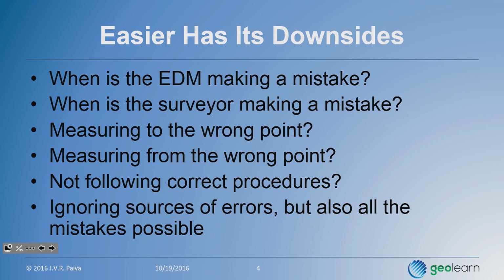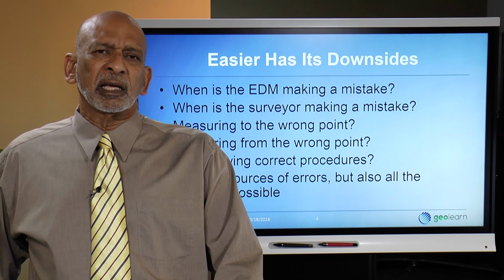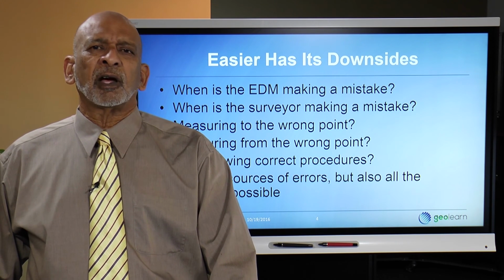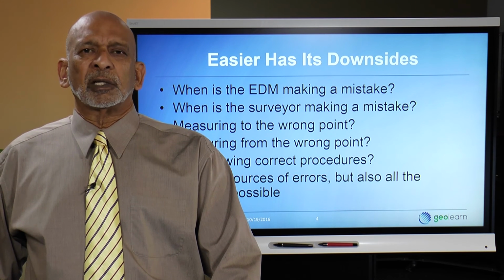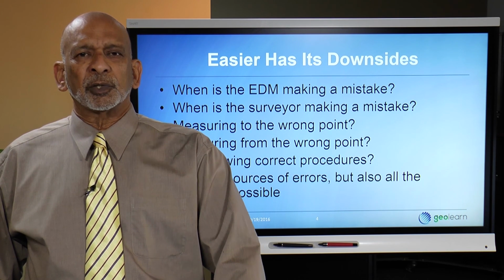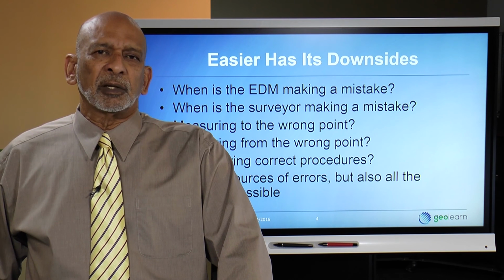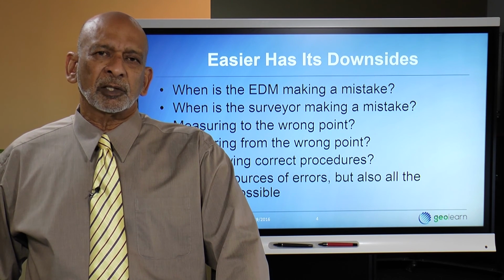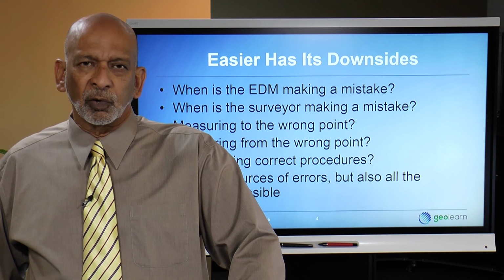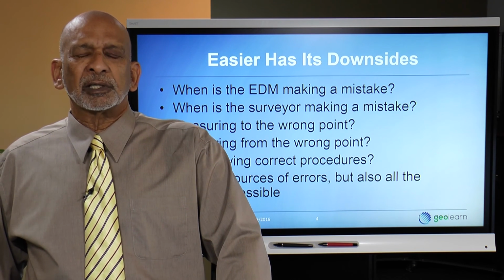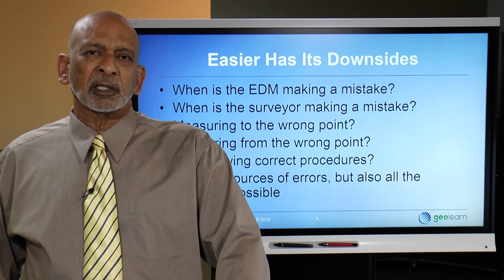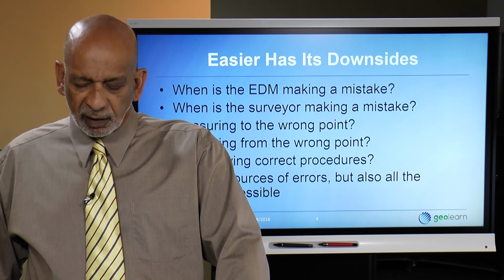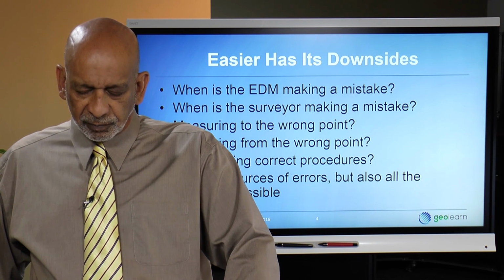A big occupational hazard, it seems like, in surveying is that there is an attitude of, I'll figure out how this machine works, rather than learning the proper way. And as soon as you get a result, you assume that it's working properly. So it's a really great idea to actually read the instruction manual with instrumentation that you have never seen before, because there are often fine points that come up that you may not be able to detect simply from pressing buttons and figuring out whether it is generating what seems to be the correct result.